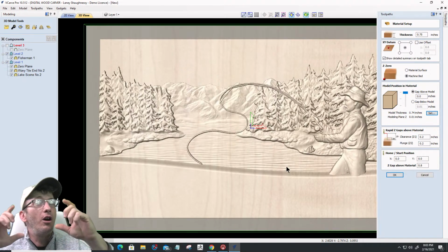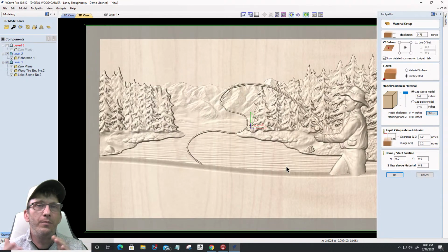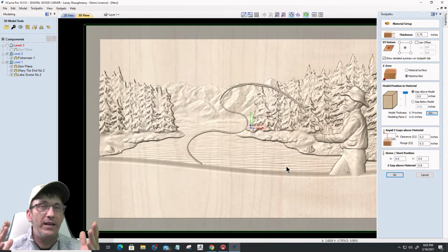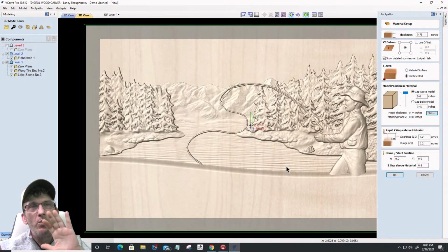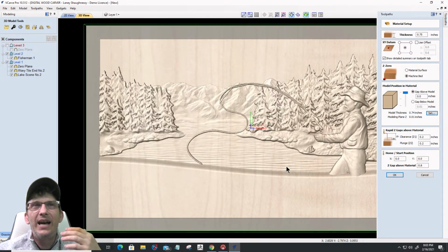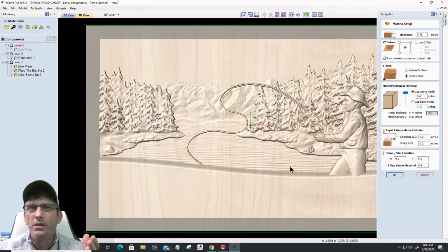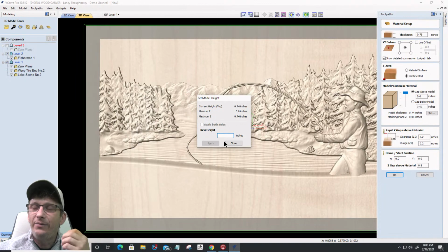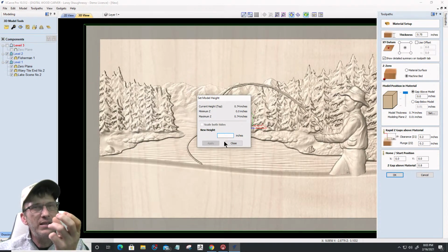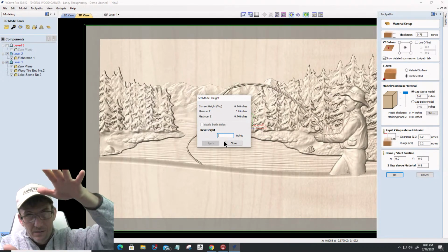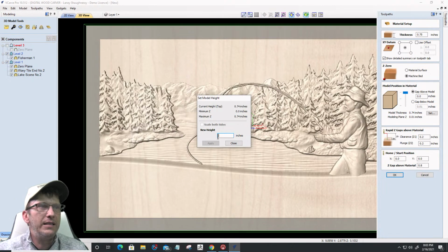So does that mean if this is my model and this is my size, do I want to go ahead and just carve out of a 1-inch thick material, 7/8 or something like that? Or do I want to reduce the model thickness a little bit more? And in my case, I'm going to stick with 3/4. And I'm going to resize the model down some, but I have to understand, the more I resize the model, the more detail I sacrifice. Okay? As that model gets smaller, I'm sacrificing detail.